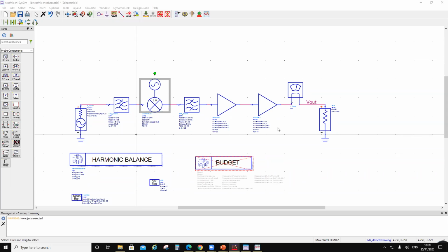Okay, so now your crest factor for that modulation is 6.7. So 24 plus 6.7, you should be able to do a 1 dB compression at around 31. Same thing, let's say a system requires 16 dBm or 19 dBm out linear. So 19 dBm linear means that for that 802.11, the crest factor is 6.67, right? So add 19 plus 6.67, that should be your 1 dB compression point. And then you do the assessment of TOI 11 dB above and 9 dB above.